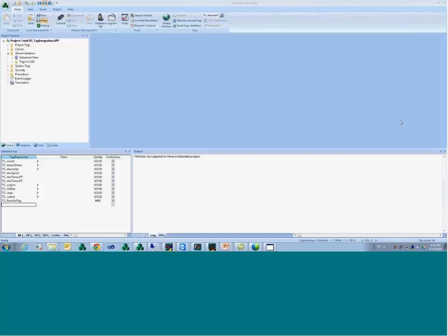And you also may know now that OPC UA is not only on the HMI and the PLC part. TwinCAT can also be an OPC UA client. And you have, for example, OPC UA clients for SAP. So you can have your SAP or your enterprise software talking directly to the PLC, sending purchase orders or getting status from the PLC, not even passing through us, through the HMI that used to be the bridge to that. So OPC UA is a very powerful technology. So if you want to use that all across the board, you can use InduSoft for the OPC UA as well. Okay? All right, so let me read another question here.